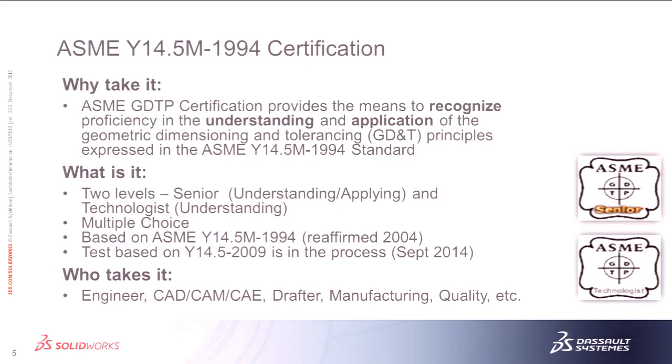The first 2 chapters of the book are nothing but examples on standard ways to dimension and tolerance parts that don't deal with GD&T at all, which is a lot about what this speech is going to be about. Anytime we get a co-op, intern, or new hire, the first thing I do is hand them this standard and tell them, read the first 2 chapters, understand it, and if you have any questions, come to me, because when you start doing drawings, it has a wealth of information that you can rely on.